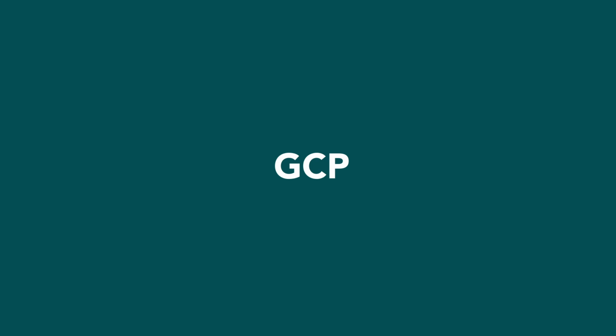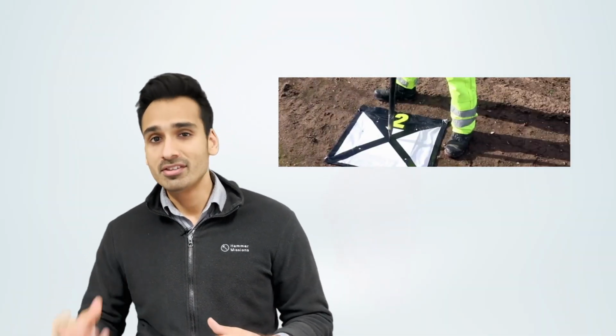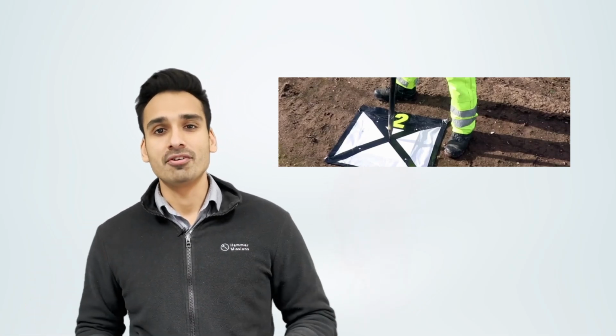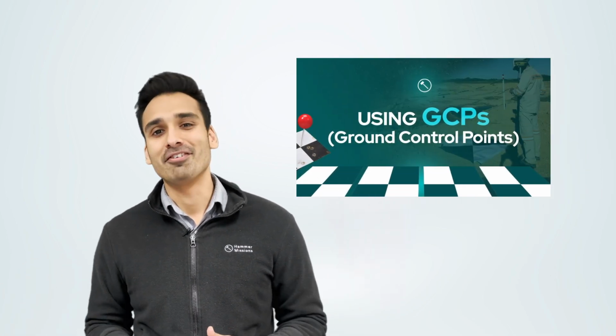Right, so the next one, GCP or ground control points. Ground control points, GCP, is really important. These are essentially just markers that are placed on the ground that are used to correct the inaccuracies in the drone's GPS. The drone's GPS, generally speaking, is between 1 to 2 meters accurate. And if you want your map to be centimeter level accurate and not meter level accurate, you want to make sure you correct for that. The way you do that is by using GCPs, these markers on the ground, and recording their positions. I've got a whole video on GCP that you can go watch if you're interested in learning more, but it's essentially a method to improve the accuracy of your drone map or model.